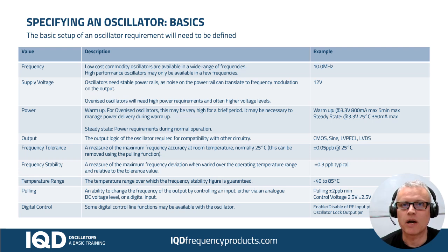In that case, I would still ask the question, when you say stopped, did you mean that you wanted the output buffer to disable, but the internal oscillators to keep running, meaning there's no output available, but when you need that output, you can switch it back on very, very quickly because internally I'm still running. But therefore the current draw, when you switch it off, is going to be about the same because I'm still doing the same amount of work internally.